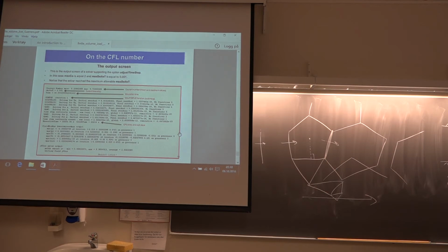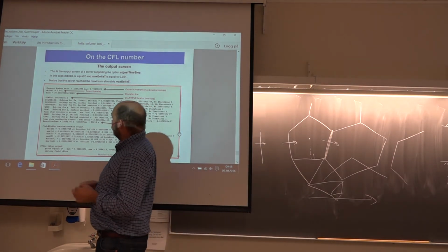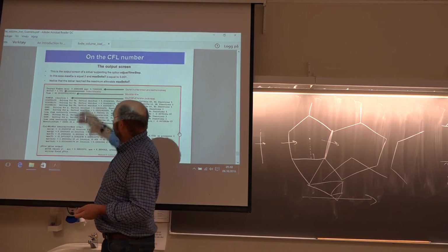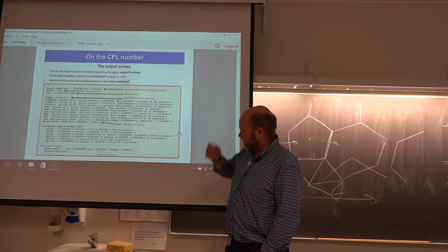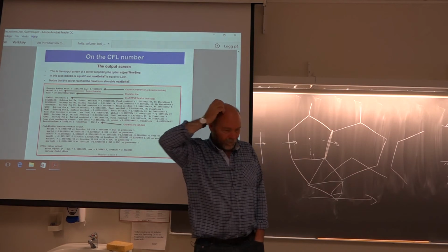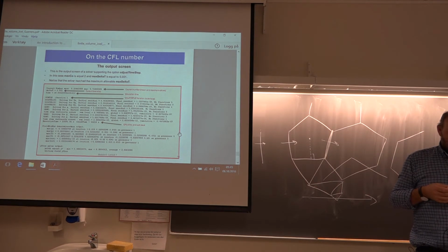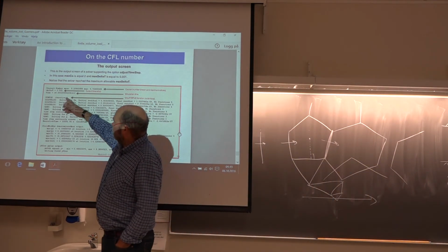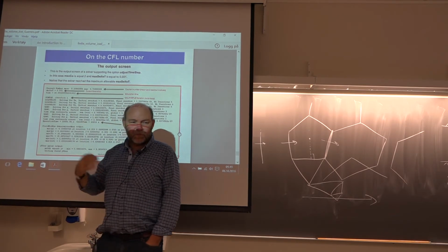I won't go through the details, but when you simulate, you get the printout, and you get the average Courant number and the maximum Courant number. So that's something you have to look into. If you run a code where they have set up this automatic control for the Courant number, then you have to be careful. You risk that it creates a deltaT that goes smaller and smaller and smaller, because say you have done something really stupid.